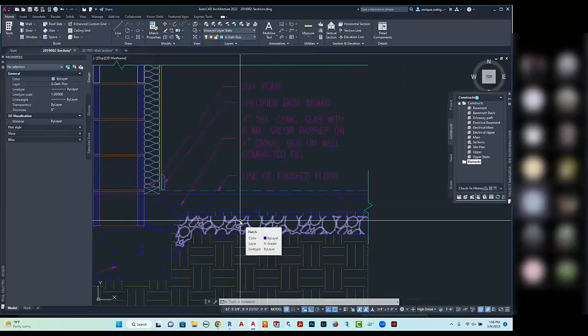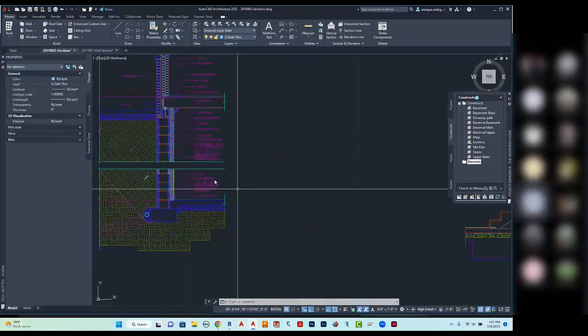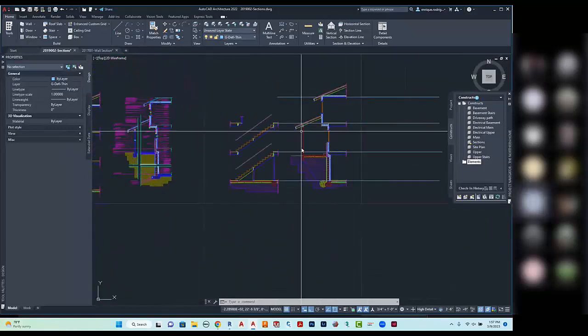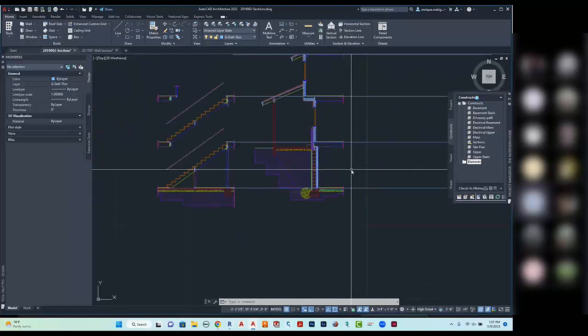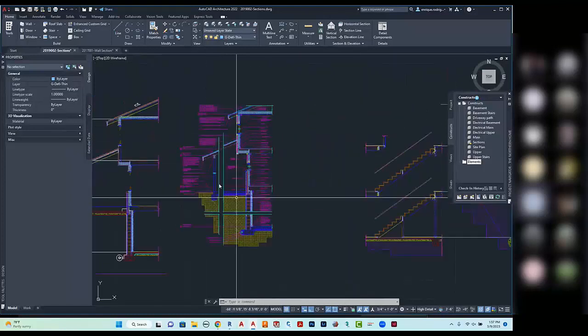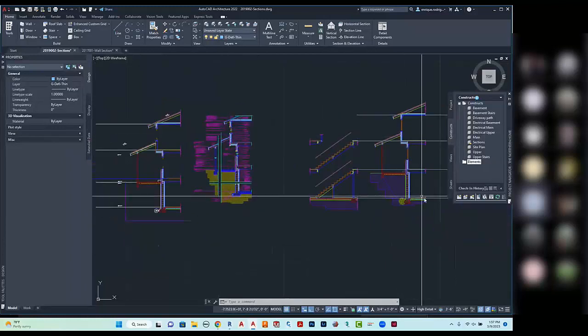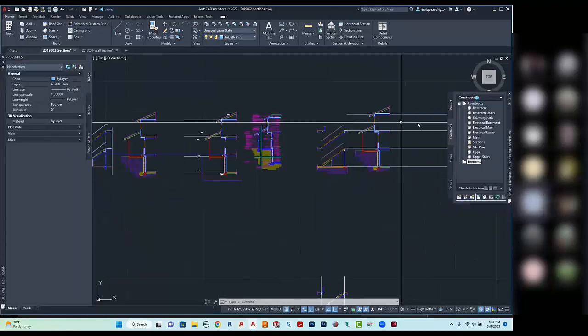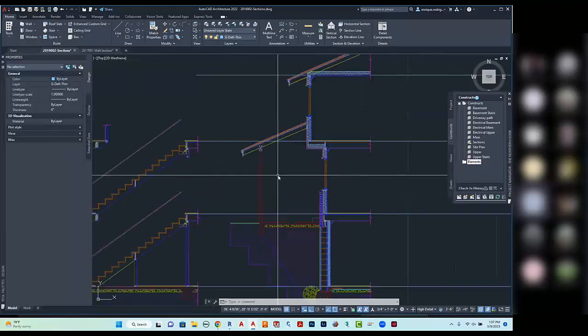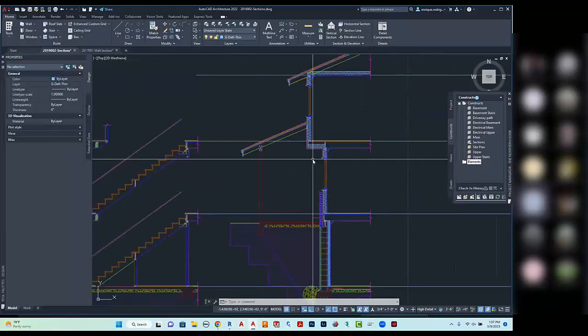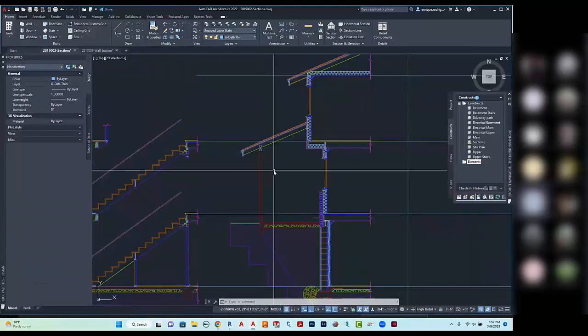And you're going to see there you have the color, layer, and line type that's indicated in here. So use hers as a guideline, which is going to be very similar to the one that I had here. Again, to repeat, do not draw it like this with the break lines. I want full height, floor to floor as it's supposed to be, including your distances, horizontal and vertical.